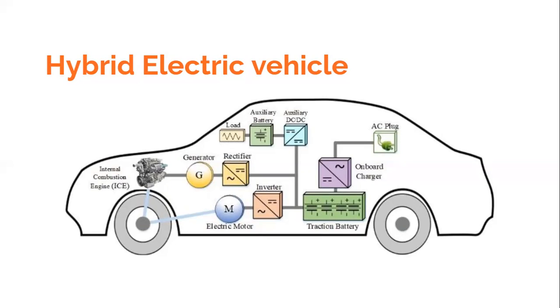If you want higher speed or higher power, then this hybrid electric vehicle would switch to internal combustion engine for propulsion. These two drivetrains, that is both the electric drivetrain and the internal combustion engine drivetrain, can work together to improve the performance. So this is the beauty of hybrid electric vehicles. It would enhance the performance by filling the gaps between the gear shifts and providing speed boosts when required.